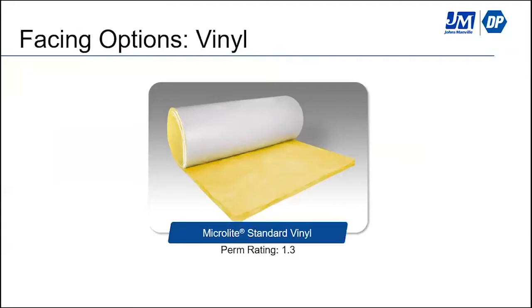Another facing option that we have is our Microlite Standard Duct Wrap Vinyl Facing. It has a little bit higher perm rating, as you can see, 1.3, so it's not near as good as what your FSK or your PSK facings would get. It's a very multi-purpose product that gets used in a lot of different applications. We've seen it used for removable valve covers. Some people will use it on some duct insulation. I've seen it used in chicken coops. It's a very multi-purpose clean face, and the vinyl stretches a little bit more. It doesn't have that reinforcing scrim in it, so you can pull it a little bit. It's good in places where you might need something that's white or a clean look, something that's cleanable as well. So just another option that's out there that we offer as a facing.